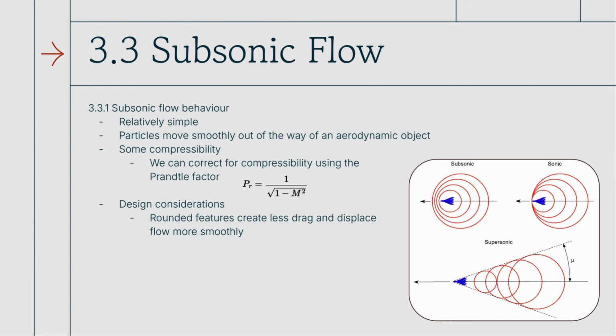The molecules right at the nose of your vehicle get imparted with some momentum, and they move forward at the speed of sound and smash into other particles, and those smash into more particles. So they are getting a warning through this pressure mechanical wave that's propagating ahead of the vehicle. That's what I mean by they have warning, because the wave is physically traveling through them. Kind of just like billiard balls, like pool table balls.